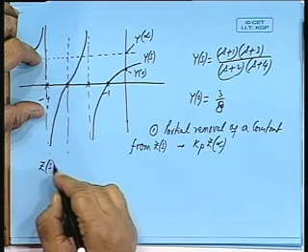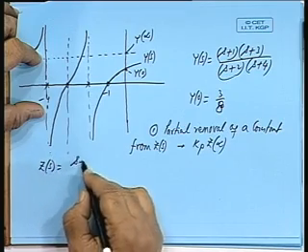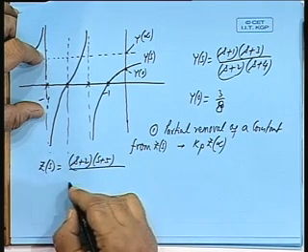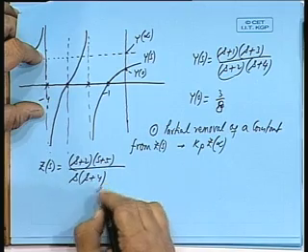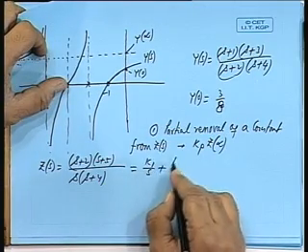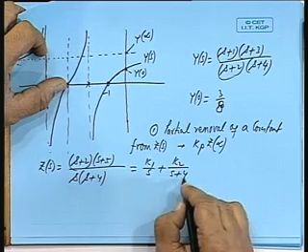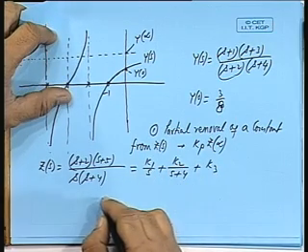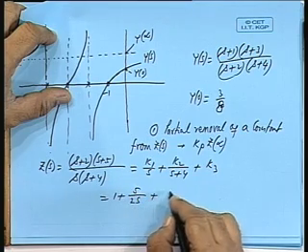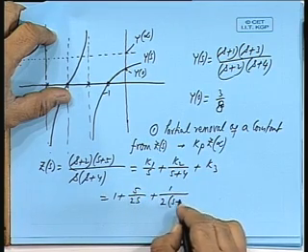So, let us go back to that very example. Zs is s plus 2 into s plus 5 divided by s into s plus 4. So, if you make a partial fraction, K1 by s plus K2 by s plus 4 plus K3, that gives me 1 plus 5 by 2s plus 1 by 2 into s plus 4.